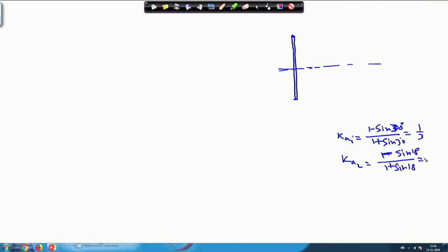That value becomes 0.52, and 1 by 3 means 0.3333. Since gamma is 18 and the depth is 3 meter, it will go linearly. So this value will be gamma 18, H 3, and Ka 1 by 3, so this becomes 18 at this point as the pressure intensity.